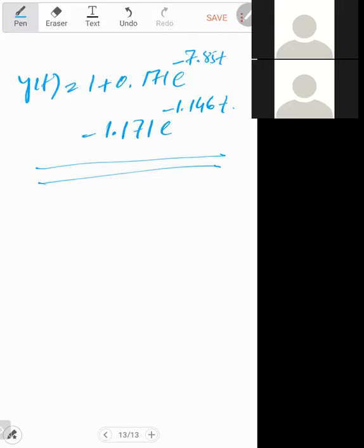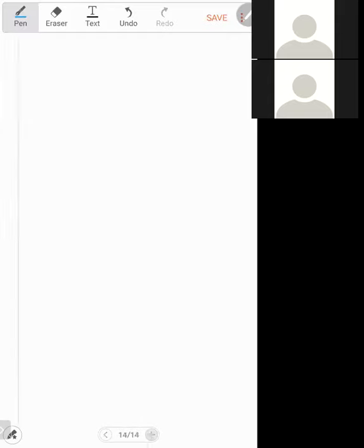So similarly, you can find it for other second order functions also, if you know the equation, and especially if you know the value of zeta, which should be greater than 1. So let's say that g of s is equal to what? G of s is equal to the same case, 9 divided by s square plus 6 zeta s plus 9.